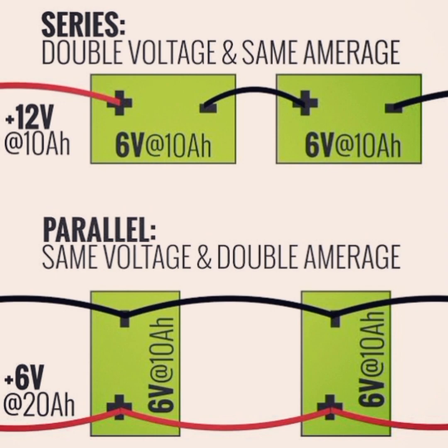As I said, in a series connection, when we connect two 6 volt batteries in series, it forms an addition of voltage and makes 12 volt, but the ampere hour remains constant in a series connection. But in a parallel connection, the voltage will remain the same, and the ampere hour, which means the current rating, will increase when we are connecting in a parallel connection.